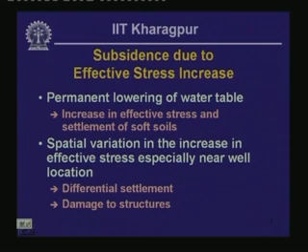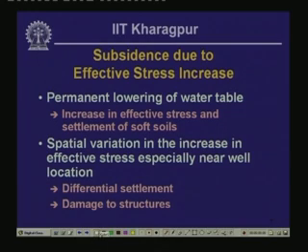Now the second problem that is of engineering relevance because of groundwater overutilization is subsidence. Why is subsidence going to be triggered? Subsidence is going to be triggered because of the lowering of the water table and the effective stress increase that occurs because of it. Now if you recall, I have already talked about it in detail earlier on.